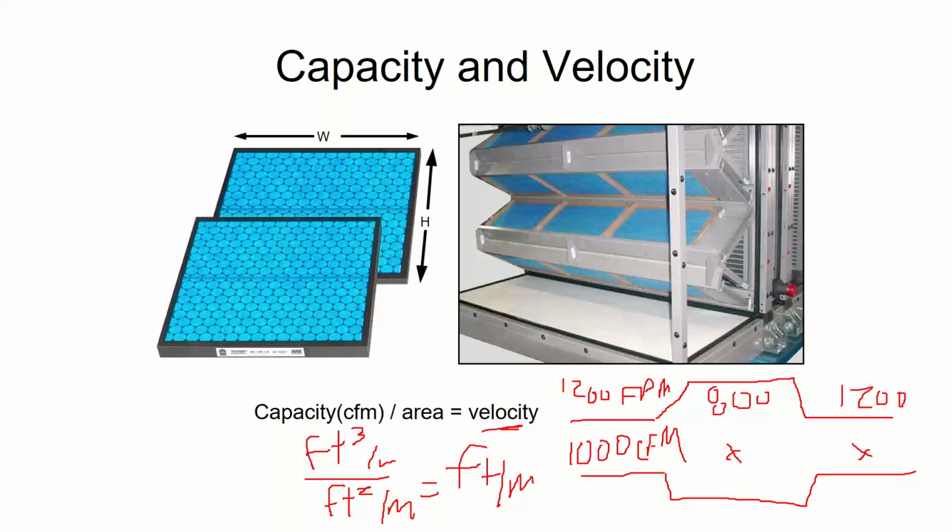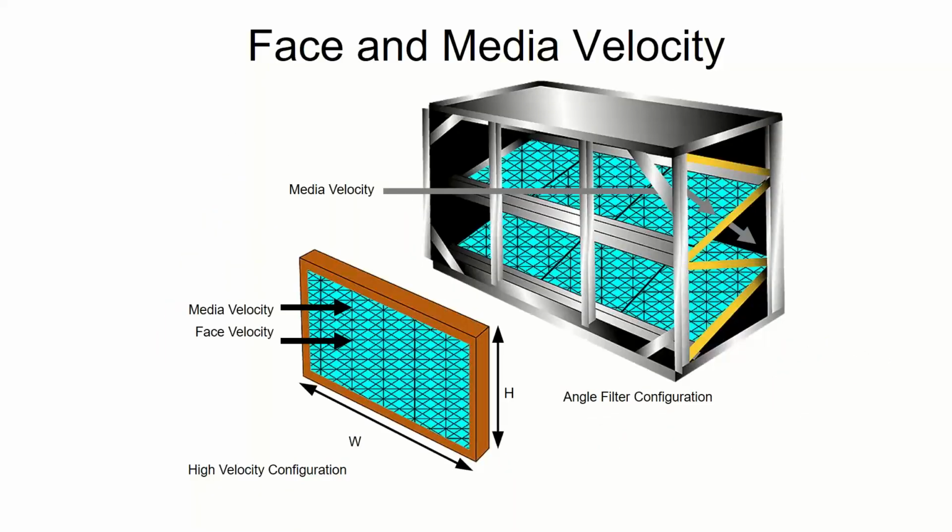So if I want to have the air slow down, I need to make the dimension bigger. If I go in your building and say, hey, the ductwork coming in, let's double the height of that ductwork and put some more filter in that way and get more filter surface area, you'll be like, dude, there's nowhere to double it. We don't have that kind of space. So what you get in a lot of cases is this V-bank scenario where I have all that surface area. If you stretch out those filters like an accordion, it's a pretty tall duct. I just happen to put them in a V shape to get them all to fit. So as the air goes through the V-bank, it temporarily slows down for that instant. And then as it leaves the V-bank, it's back up to the regular velocity. So that's one way I can do it.